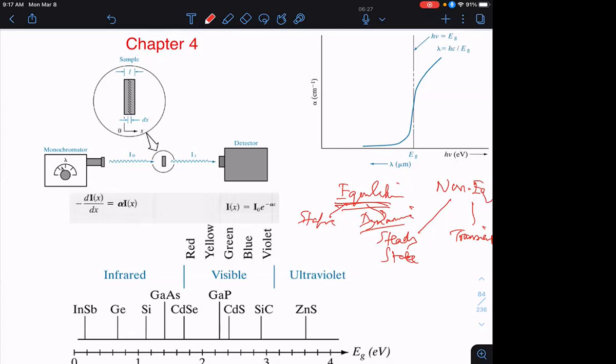Well, in the case of semiconductors, it's definitely dynamic equilibrium when it comes to carrier concentrations. Why? Because we saw that in a semiconductor, you can excite electrons from the valence band to the conduction band and create a few conduction electrons, leaving behind positive holes, even in the absence of doping. But then after a few nanoseconds, these electrons and holes would recombine and give off photons to the ambient. After a few nanoseconds, you could absorb a photon from the ambient and re-excite an electron-hole pair.